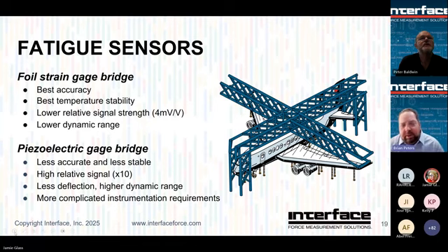But piezoelectric, another option, is good for impact style testing, less accurate, much less stable, and they're inherently just designed to only measure a change in force. So they're not going to be good, certainly, for any sort of static or long-term type loading. High signal, which is a positive, but again, very high sensitivity to temperature. But they're going to be on a very stiff element, good for natural frequency, which we'll talk about, but they do require very specific and much more complicated instrumentation.